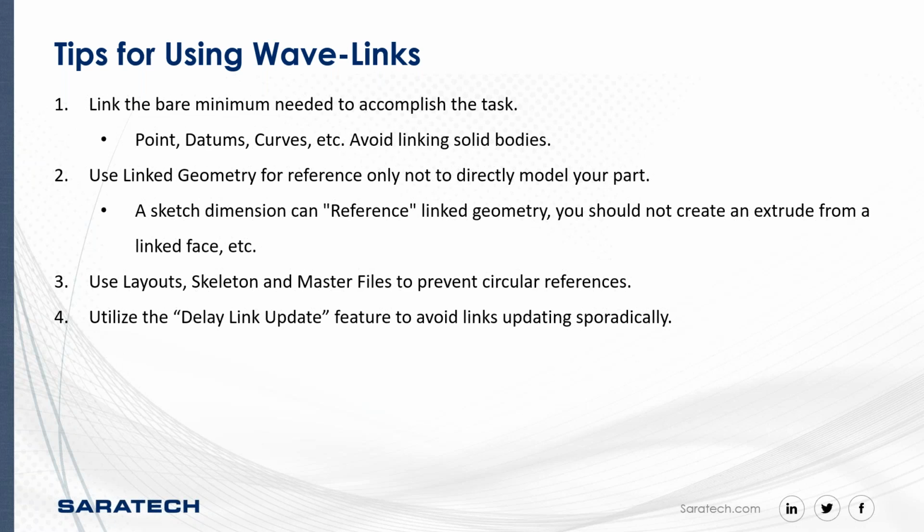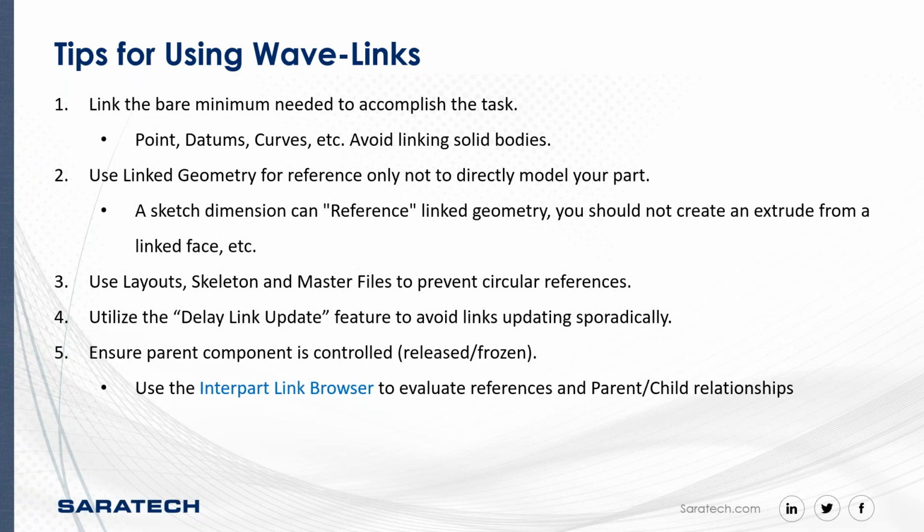Utilize the delay link update feature to avoid links updating sporadically. So again, you want it to be controlled. So go ahead and toggle on that delay link update. When there's an update that does occur, you can catch that right when it happens rather than it happening while you're making edits.